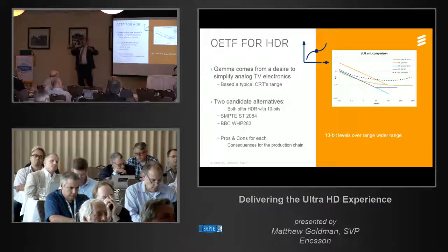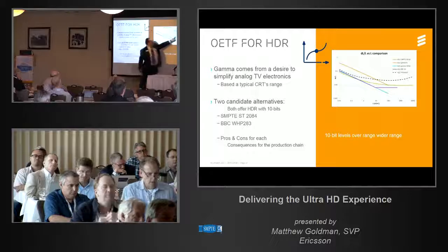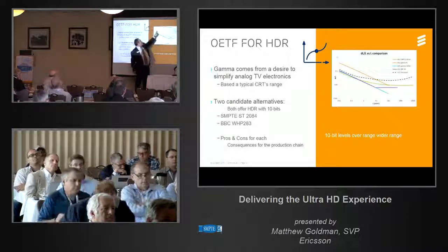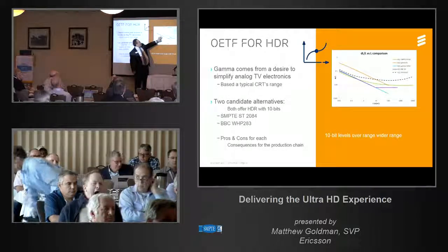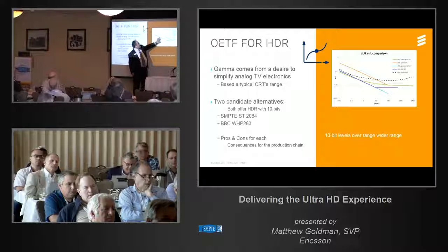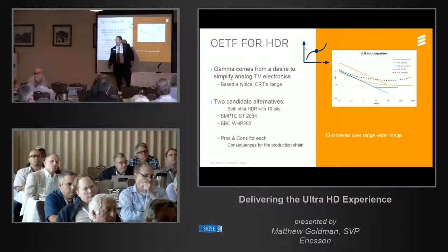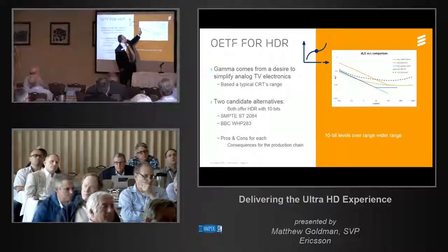So, that conversion factor for OETF, optical electrical transfer function, or electrical optical, doesn't matter which way you go. We're using this example here. This matches the Barten curve, the human sensitivity curve. You want something that closely matches that. That's the 8-bit gamma we have now. If we move it to 10 bits, it slides down here. But this is with standard dynamic range. If we now go to much higher dynamic range, it's going to slide the curve this way.